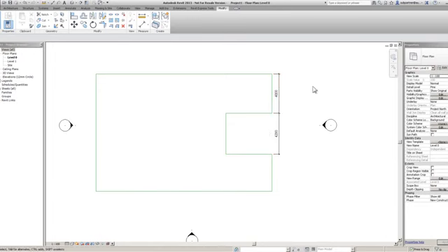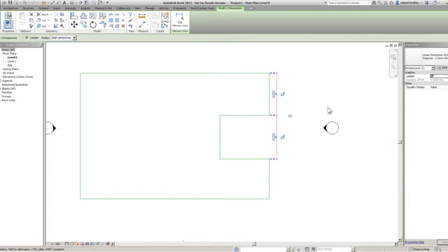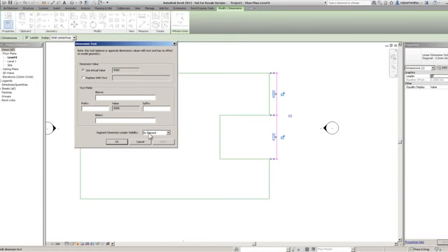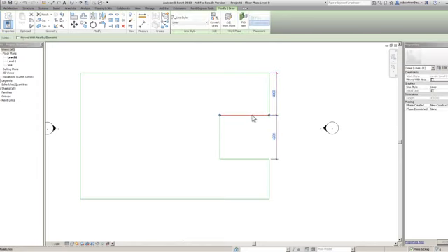Now, let's try this. And this is what confuses people when they first start to use it, so I'm showing you. Let's just say you want to change that distance there now to, I don't know, back to 3 meters. What people do, when they've got a permanent dimension there, they go, right, I'm just going to select the dimension. So it's selected that dimension. Let's pick the actual dimension again. Oh my hell, what's going on here? What's that box? Panic. Now basically what's happening is that's a different mode, we'll come to that in a second. To move that line, you still have to select that line.